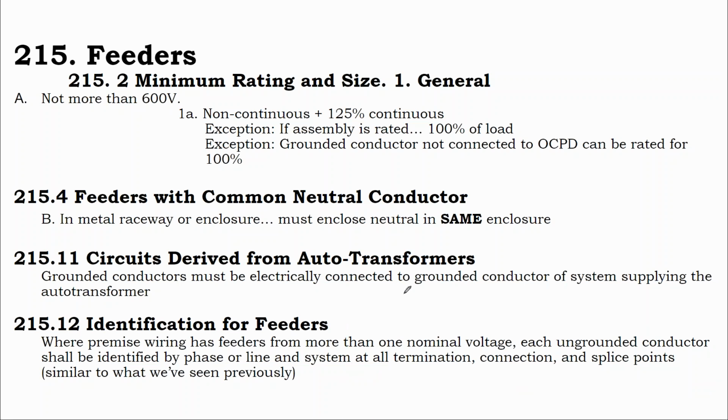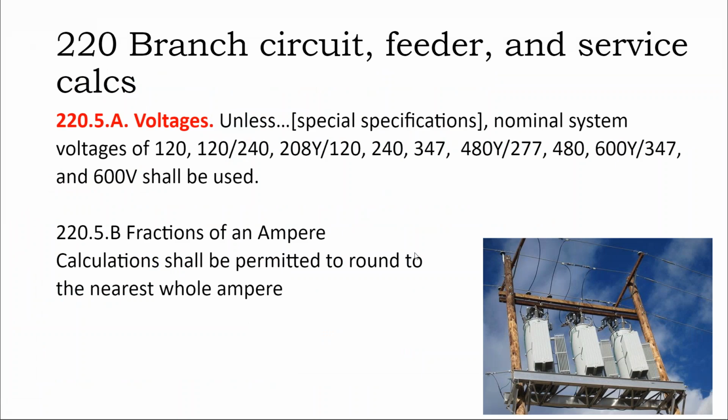They call it a special photovoltaic output circuit. But still, you have to label the boxes and the conductors. Feeder circuits have to be similarly kind of over labeled.